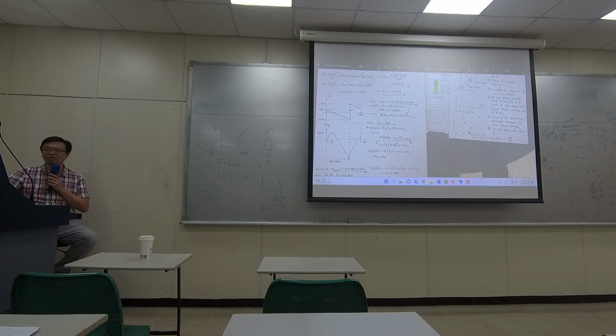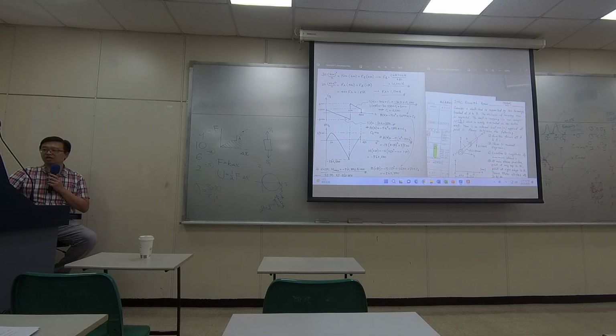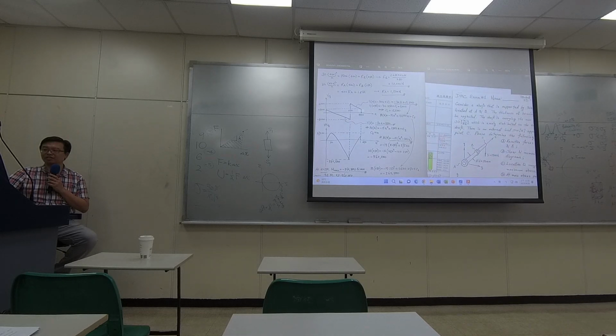And I know the slope of this line because I know how much the distributed load is. Every millimeter I have 30 Newton. And I know it's definitely going down because of the weight. So whenever I move by 1 millimeter, it goes down by 30. Then that's indicating the slope. So if I move up to 250, I can compute this point. It's going to be negative 6,000.